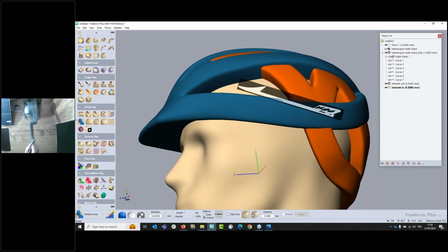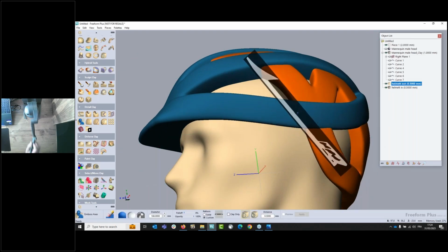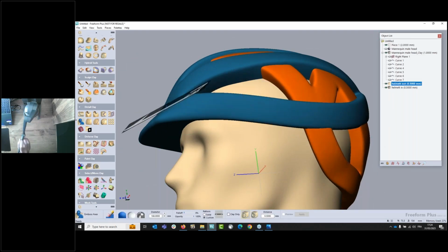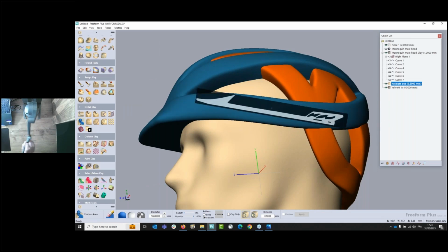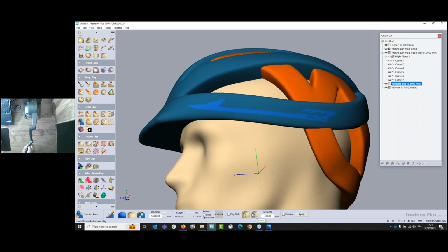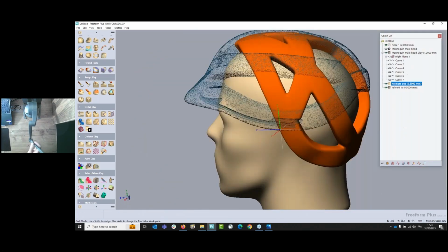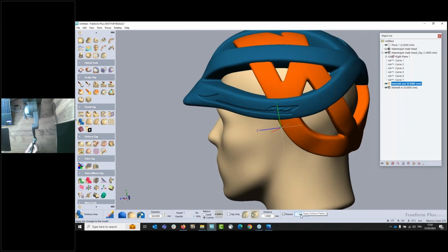When I touch the object, Freeform will automatically, if I activate this one, of course, adjust the tangency on my object. So let me click here. Then I will ask Freeform to emboss this arrow by 1 millimeter. Ask for a preview. Of course, it will follow the shape. Then I can apply.